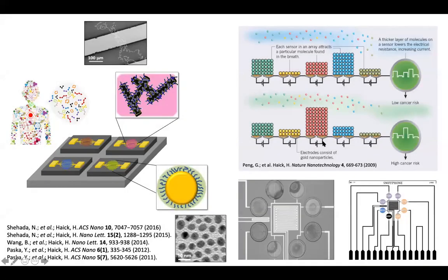Okay. So first of all, we don't have any chemical reaction in this case. So this will allow us to make the recovery of the sensor. So we have gold nanoparticles in this case, as could be seen here, which are coated with organic ligands. And the organic ligands have a functional group that doesn't react chemically with the other functional group on the other side of the nanoparticle. So if you have one nanoparticle and the other nanoparticle, they are separated by the ligands, but they don't react chemically. And therefore, if you build a film of these nanoparticles, the molecules will penetrate throughout these nanoparticles inside, and they will do one of three mechanisms.